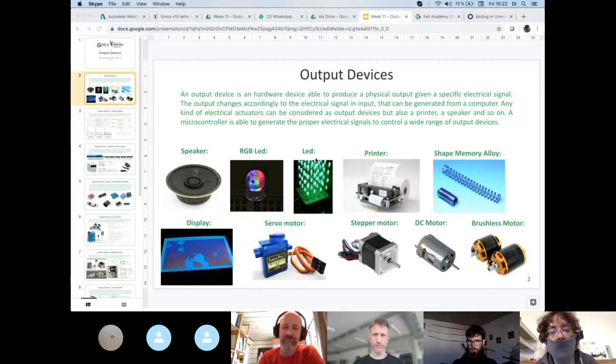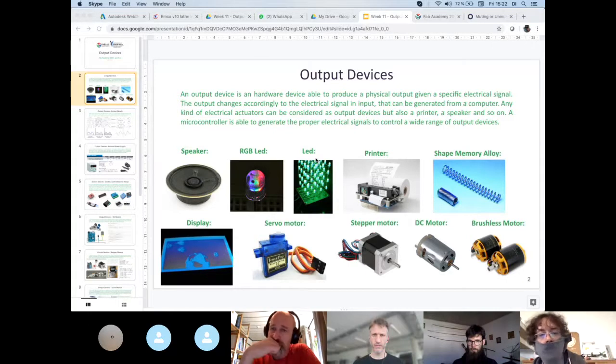So there are some LEDs that will just vary along all the range, or some LEDs that are managed by an additional microcontroller. As you may remember, some input or output devices could have electronics inside. So if there is a chip attached to these LEDs, maybe you don't need the fork connection to drive it. You need maybe I2C or some other protocol to communicate, like the NeoPixels, for example.